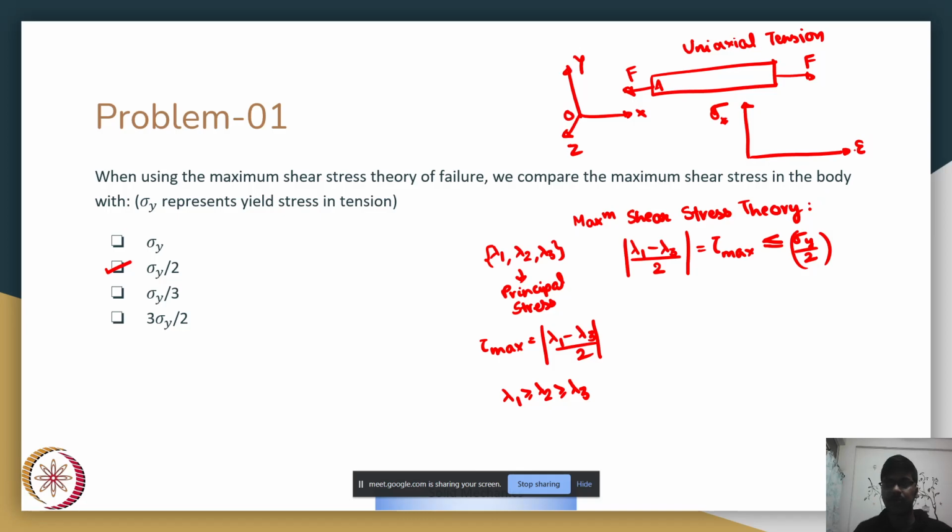So in the uniaxial tension test, we check how the body's normal stress is related to the normal strain. And when we do this plot, we initially see it to be a linear plot. This is the basis for the linear stress-strain relations that you have learned in previous classes. This is the experimental basis.